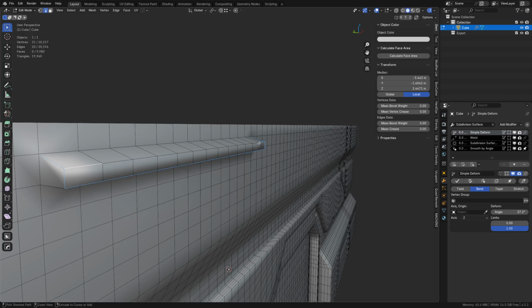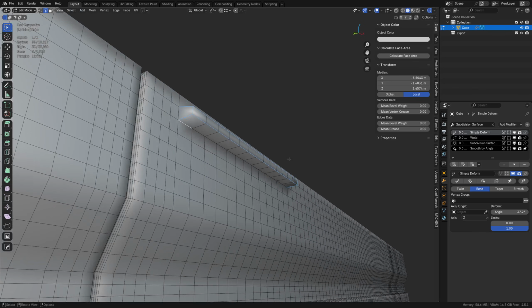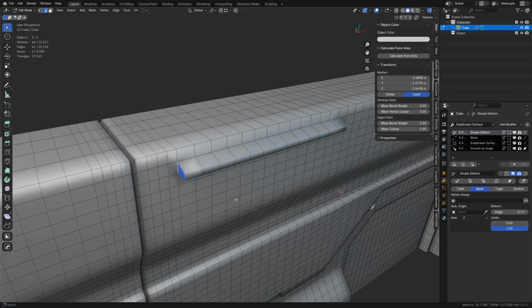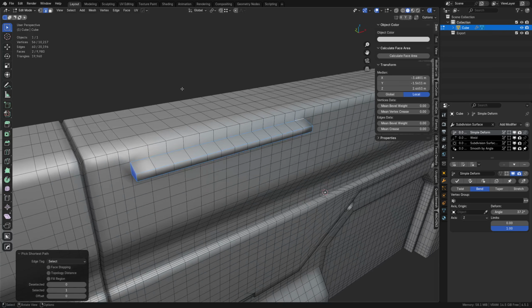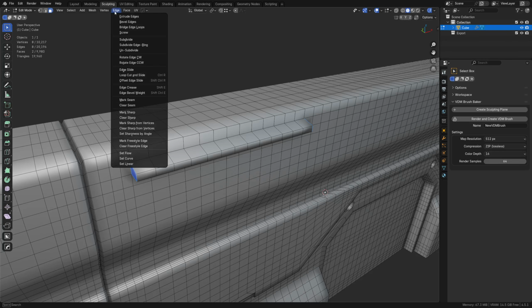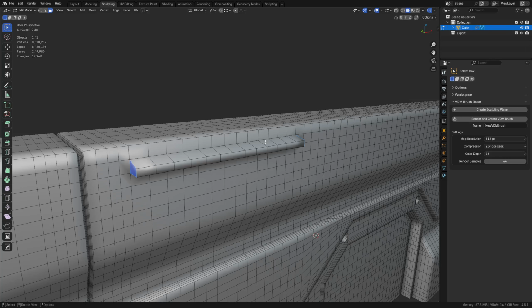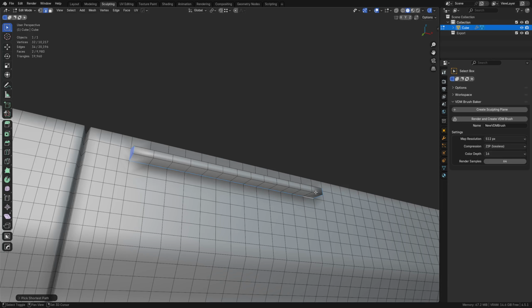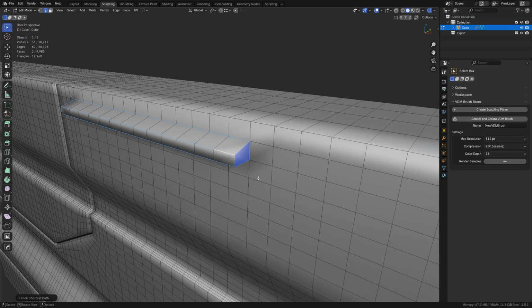Now, unfortunately, Blender used to have a select sharp edges option, and they took it out and replaced it with mark or create sharp edges or whatever. Oh, wrong thing there. Let's go back a sec. Edge. It's now set sharpness by angle, right? So they kind of got rid of that selection ability, and now that makes it a little bit harder to actually bevel things like this, which I'm kind of bummed about. But maybe they can bring it back or something.